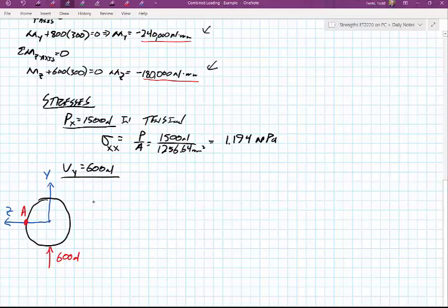The reason I know it would create a stress is because we've drawn this stress profile a number of times now. We said it's parabolic, maximum at the midpoint, and then approaches 0 at the top and bottom. So if I were looking at a point up at the top or bottom, it would be 0. But because I'm at point A, I do have a shearing stress, so I have to look at that Q, which is the area, my A prime y bar prime. The equation for that is tau is equal to VQ over IT.